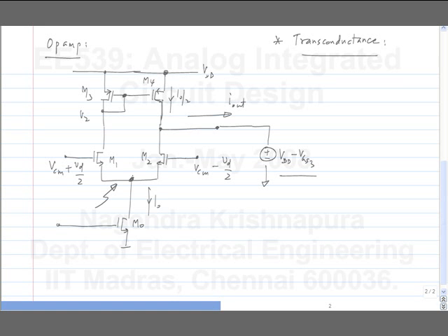So what I'll do is, but it is 0 in some conditions. It is close to 0. It's not exactly 0. If you calculate that problem in the assignment, which has the differential pair terminated by two different resistors, R1 and R2, you will find out exactly the conditions under which it is 0. In fact, that's also the reason why I chose to do it like this: I calculate the output short circuit current, then I calculate the output resistance, and from the two I calculate the voltage gain. So in this case, it turns out that this Vx is approximately 0.